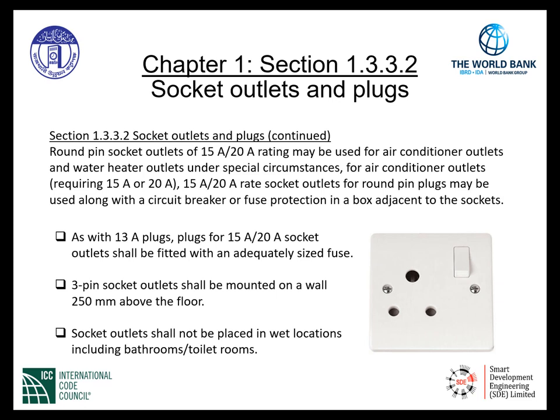Round pin socket outlets of 15 amp, 20 amp rating may be used for air conditioner outlets and water heater outlets under special circumstances. For air conditioner outlets requiring 15 amp or 20 amp rated outlets, round pin plugs may be used along with a circuit breaker or fuse protection in a box adjacent to the sockets. As with 13 amp plugs, 15 and 20 amp socket outlets shall be fitted with adequately sized fuses.